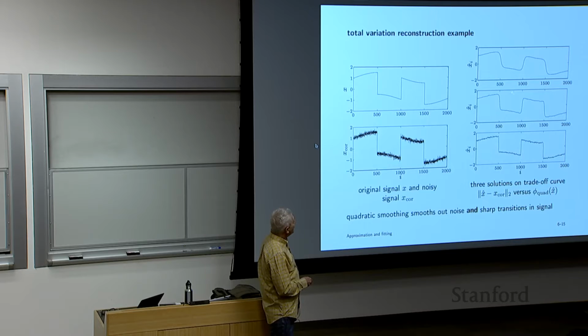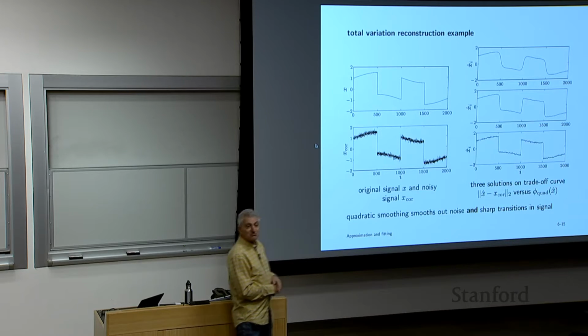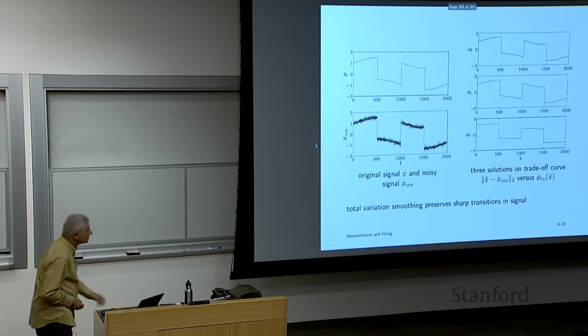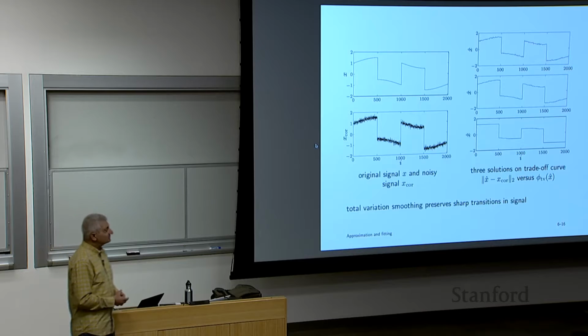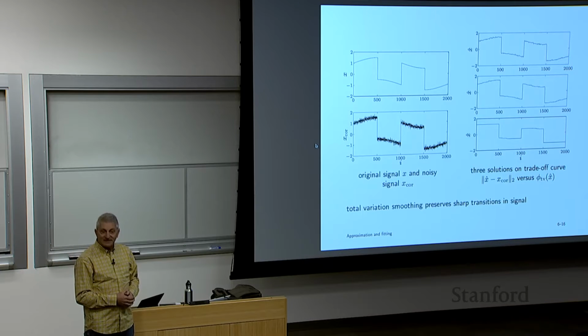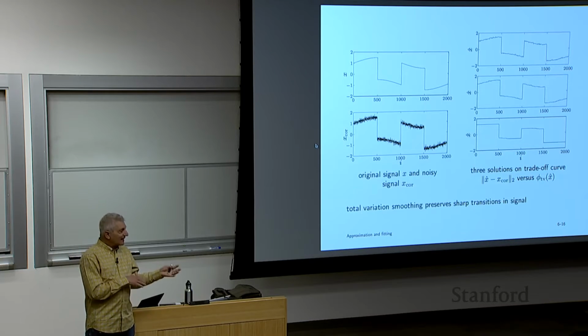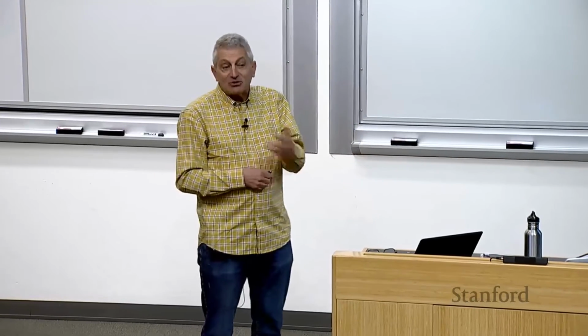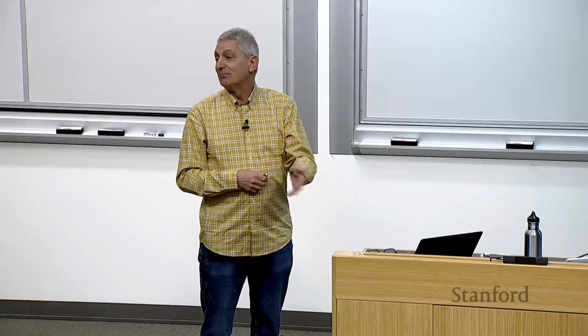Over here, when I put this amount on it, good news, the noise is attenuated more, but now you can see it's really quite smoothed, right? And then this is very smooth. So if you wanted to preserve these shifts, then instead of a quadratic smoother, you would use an L1 smoother. And this sort of makes sense. If you know about audio, this is just applying a low-pass filter, and what you're losing are, for example, the attack of a drum beat, right?